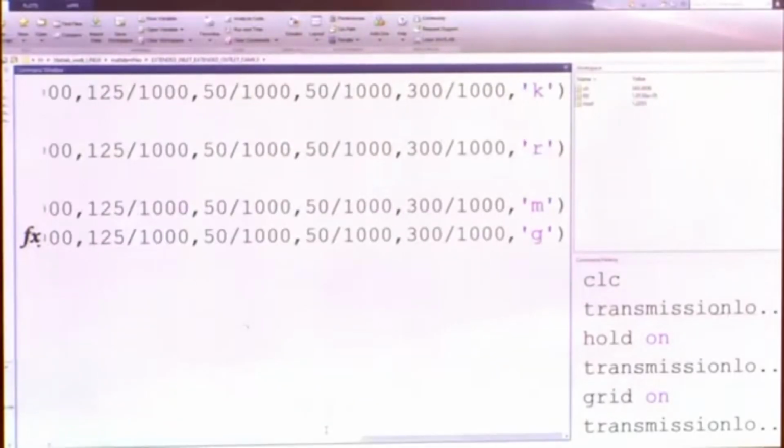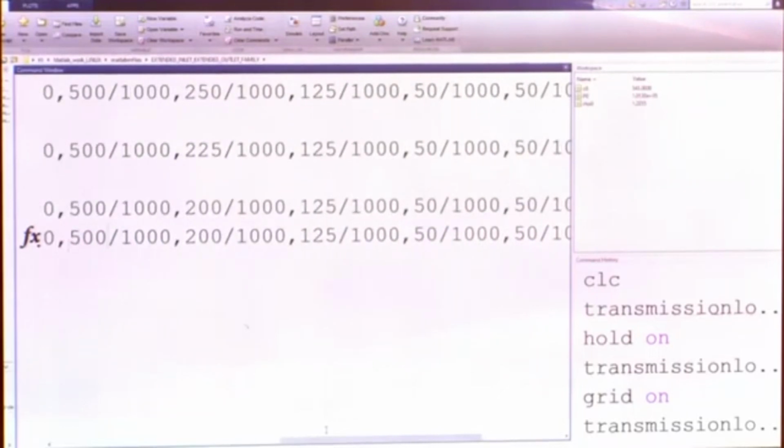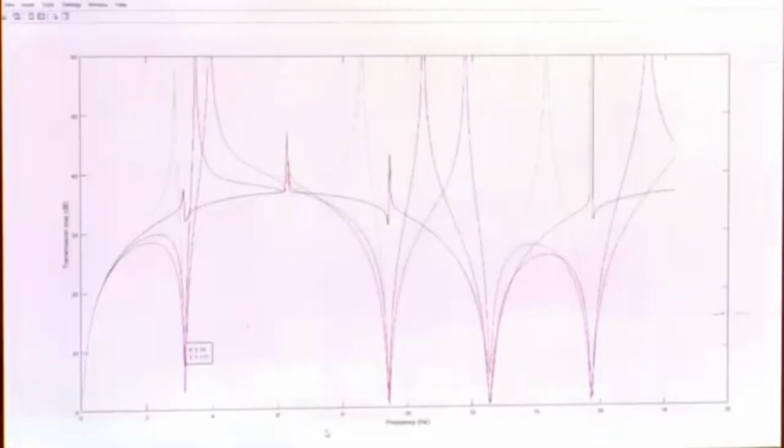This is green. On the other hand, if we consider an increased length, say 275, we will see the peaks occur slightly before the trough. So, there is a shift in the peak, and if we consider a further extension length, we will see the peak occurs at an even lower frequency. The point is that there is a mistuning: the first axial resonance trough is not coincident with the first peak of the quarter wave resonator formed at the extended inlet.